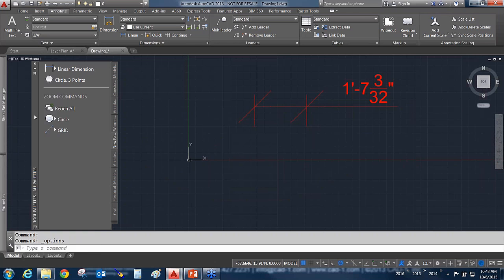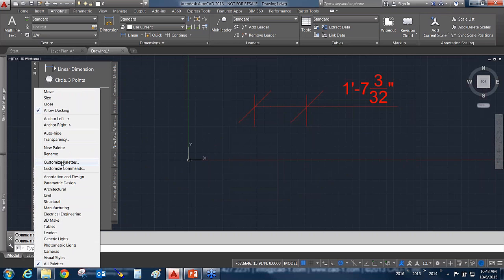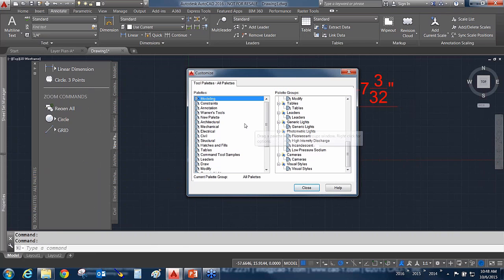So your palette groups, just like everything else, you go into your customized palettes. You can right-click in here to create a new palette, and create a new group. You can right-click over to the right to create a new group, or to remove a group. Now, one thing I did want to mention about groups very quickly, as I mentioned a moment ago, you can right-click a palette and export the palette. The palette will be exported with all of the content.